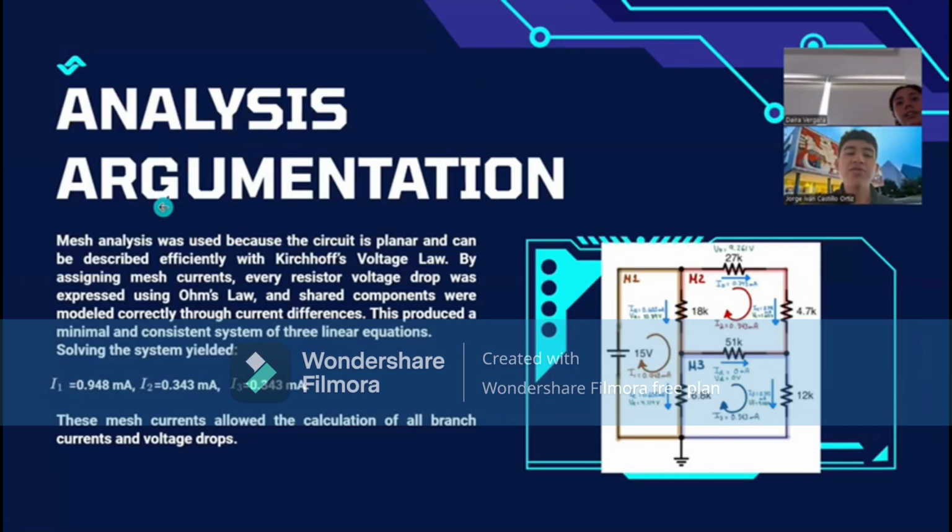For this part, as I mentioned before, the mesh analysis was used because in this case the system is planar and can be efficiently described with Kirchhoff's voltage law. With this, the equations are obtained by assigning mesh currents, and every resistor voltage drop can be expressed using Ohm's law, as we previously saw. Shared components were modeled correctly using the current difference. This produced a minimal and consistent system of three linear equations, and solving that system, we got the